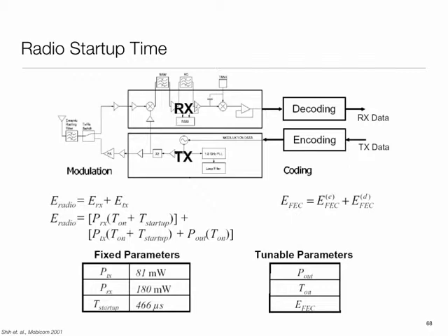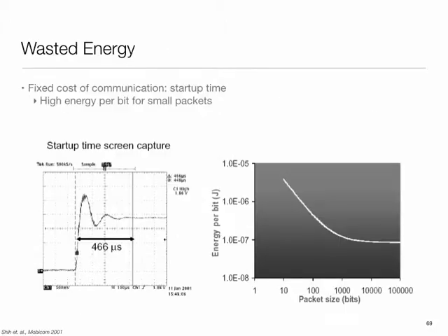So when it comes to these systems, it's important to not only think in terms of their power consumption, or for that matter, how much energy they need to do some amount of work, but also how much energy and time they take to wake up and to sleep. Because depending upon how often your workload is coming, or the size of your workload, that may become the dominating factor. If I'm sending 1 bit at a time sporadically versus large images, then that amortization will come into play. And the startup cost is entirely wasted energy, because we are basically paying for it.